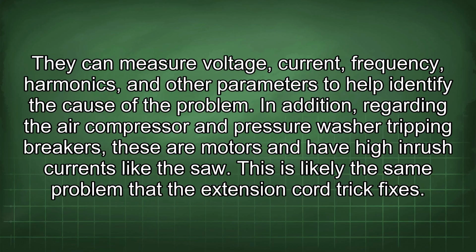In addition, regarding the air compressor and pressure washer tripping breakers, these are motors and have high inrush currents like the saw. This is likely the same problem that the extension cord trick fixes.